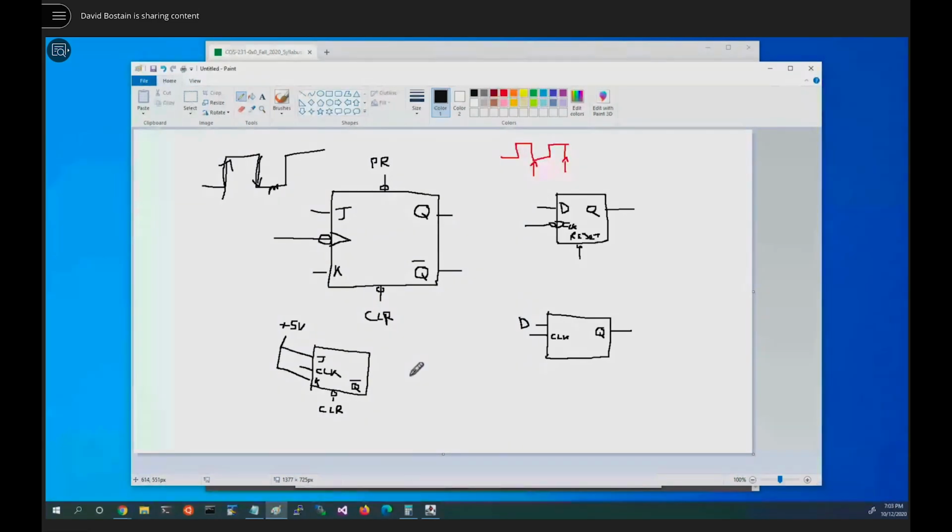So would this one be a latch? Well, maybe. What else can you tell me about it? There's only one output, and it's not Q. Okay, anything else? I'm not sure, but is that an asynchronous clear? Yep, there's an asynchronous clear.